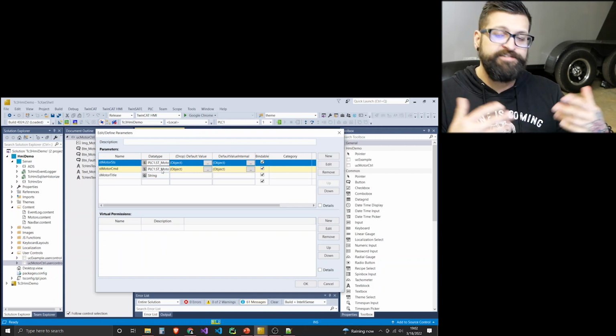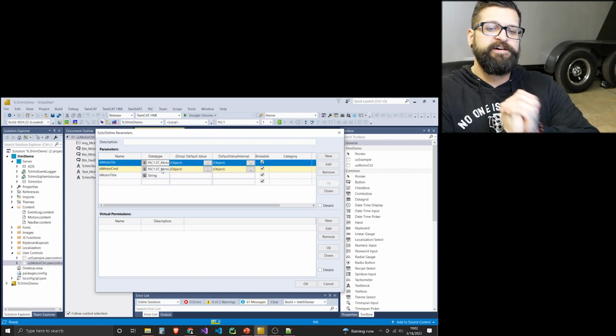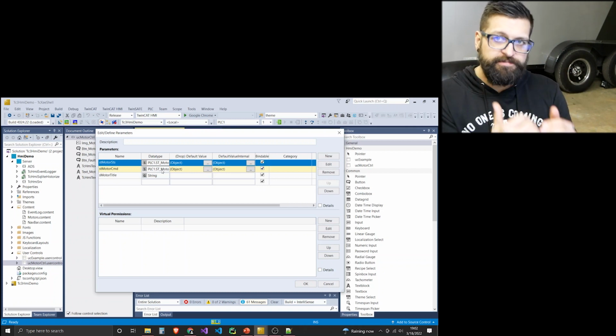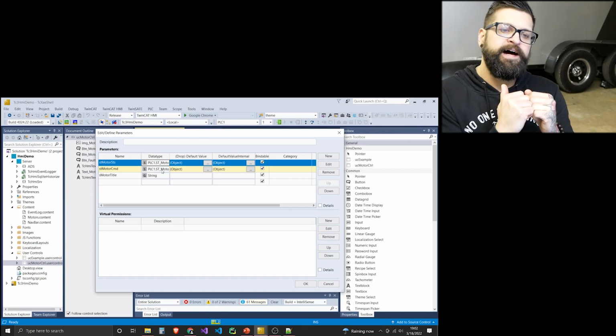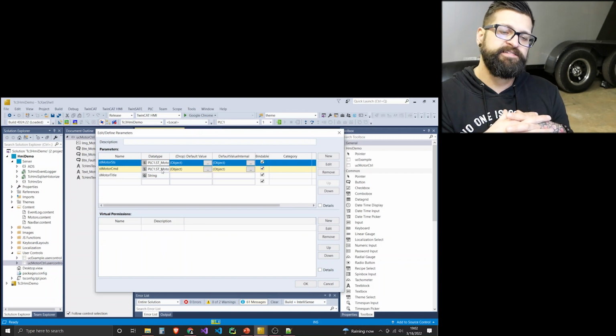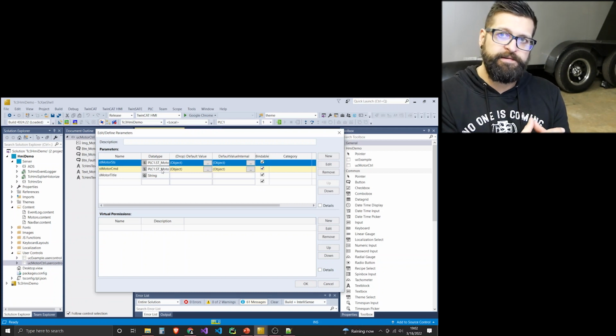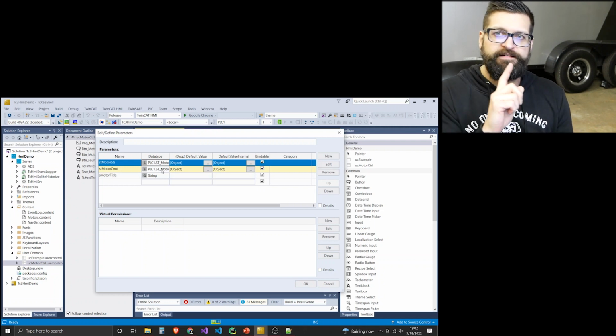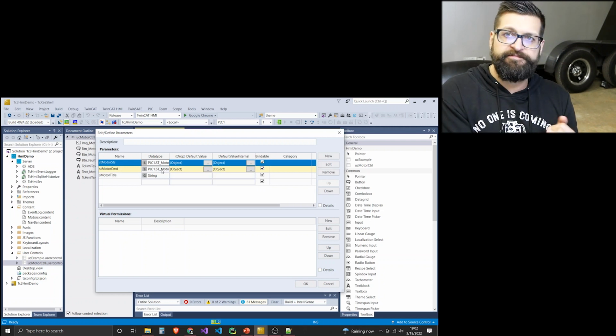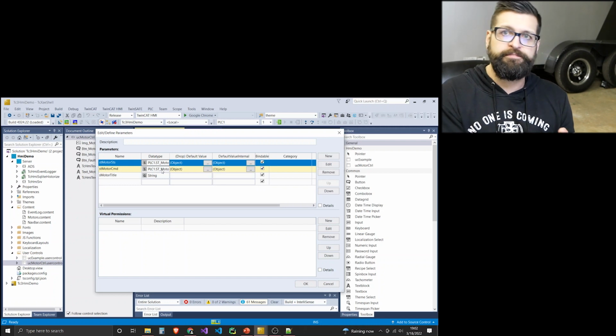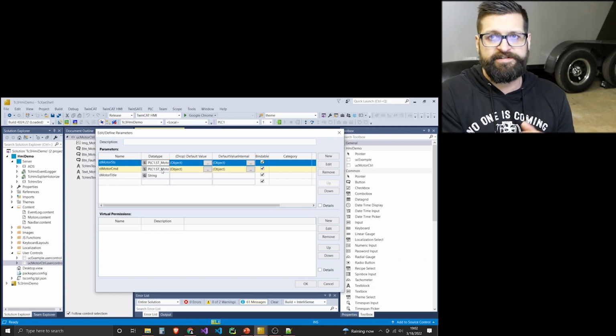And then I've made structures so that it's very easy when I've got my function block for my motor control. I'm using structures, so I have to type one variable for my motor commands and my motor statuses, rather than typing the symbol name for motor start, motor one stop, motor one fault reset.